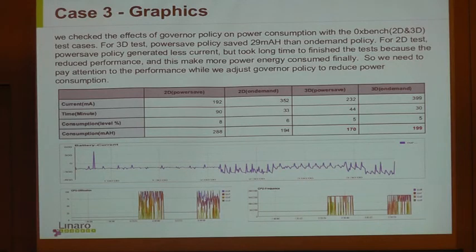The GPU can run fast, it can run slow. You might try to idle it or gate clocks between every frame, every 16 milliseconds, or you may wait until 100 milliseconds of inactivity to gate. So I was curious if you actually tested any policy around GPU power management during this test.